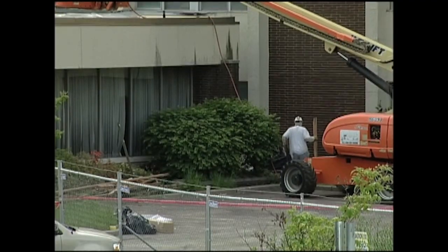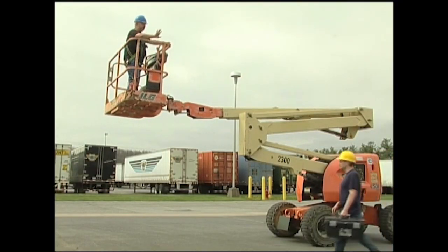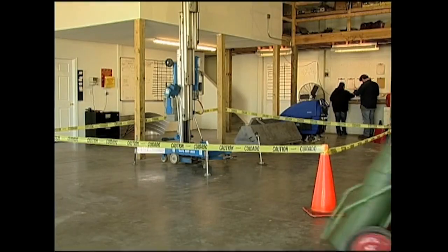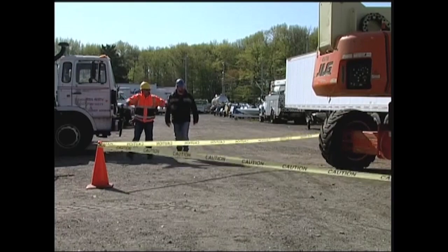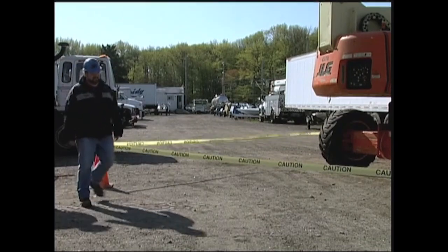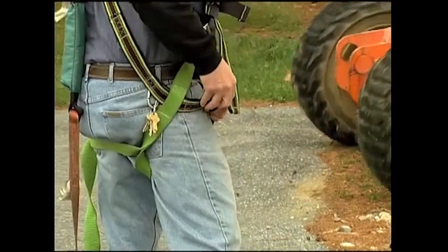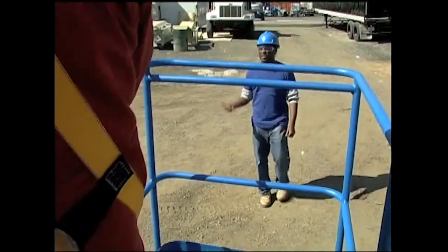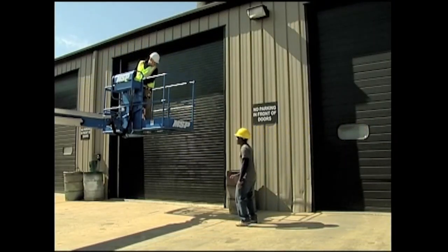Even if you're not operating a lift, you may be affected by having one around. If you're working in the vicinity of an aerial lift, be sure that you understand the hazards a lift can create. On the ground, you can still face equipment tip-overs, falling objects, even electrocution. Whenever possible, stay clear of the work area where the lift is located. If you have to go into the area, wear appropriate personal protective equipment, including a hard hat. Be on the lookout for other lifts that may be entering or exiting your work area. Be aware of the lift's blind spots and make sure that the operator can see you. And be sure to stay clear of lifts that are raising or lowering their booms.